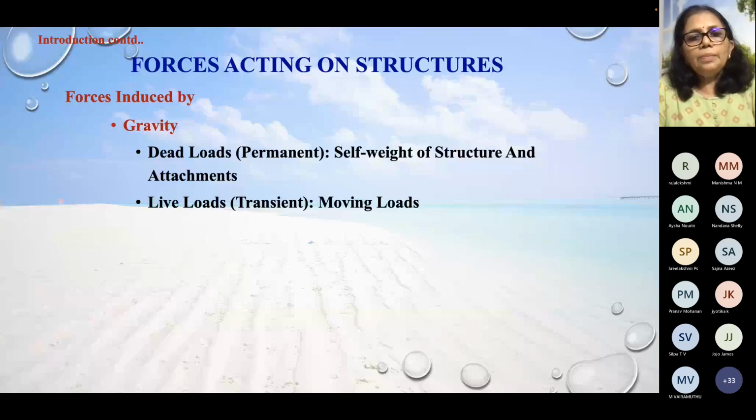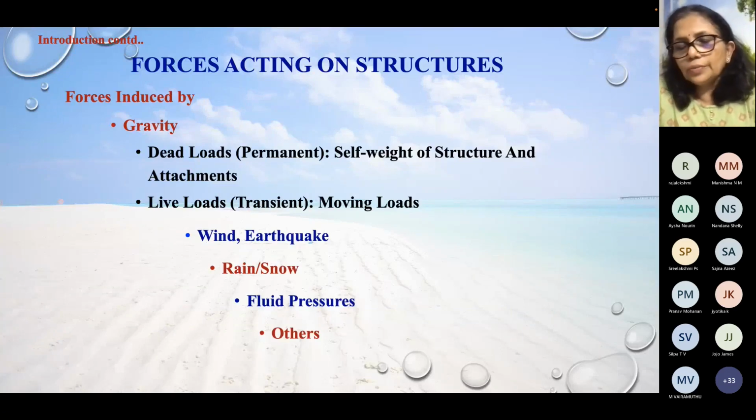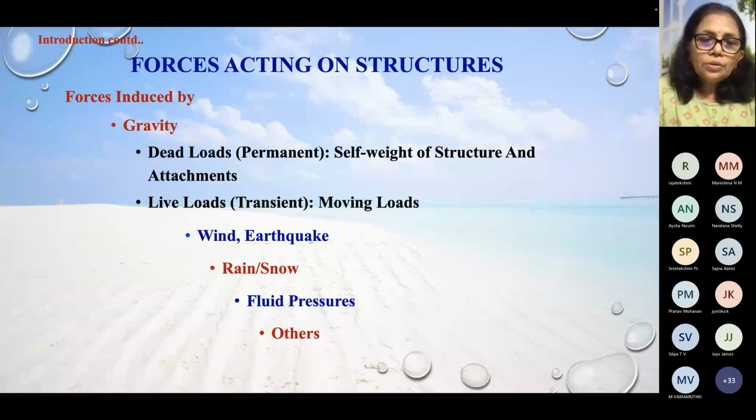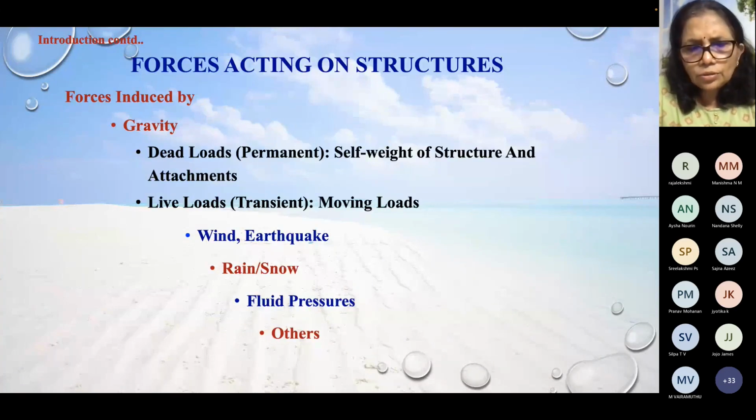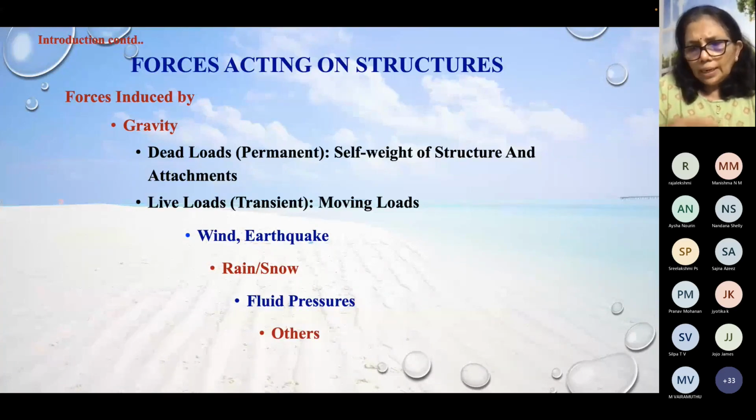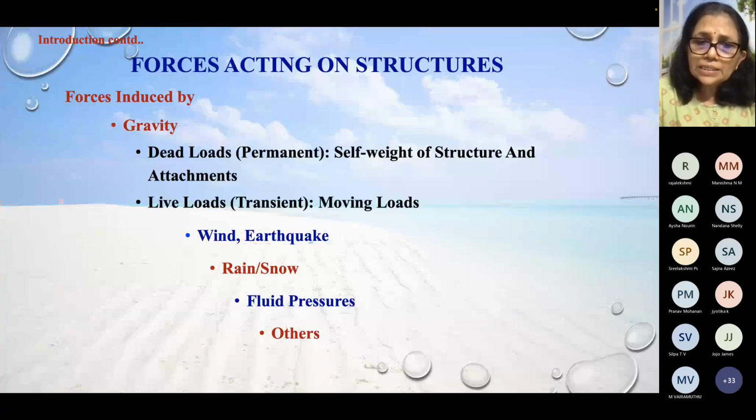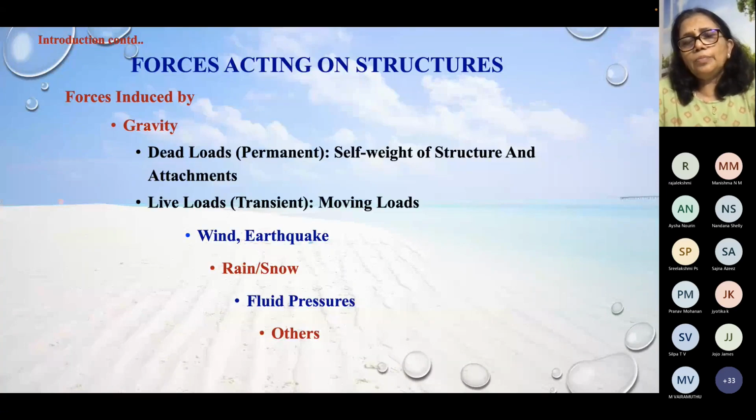Okay. Then there will be wind and earthquake loads, which are lateral loads. So more than the gravity loads, wind loads and earthquake, the lateral loads will create more problems for any structure. I'll explain that when we go deep into the session. And there will be loads due to rain and snow. There will be fluid pressures which you have to consider. And there will be other loads like machine loads.